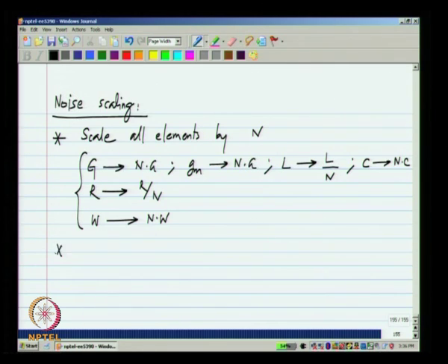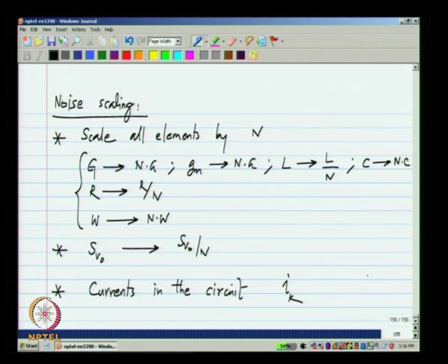If you do all of this, the voltage noise spectral density at any point in the circuit, between any two nodes, will scale by a factor n, and currents everywhere in the circuit, including the supply current, let us say I have some branch current I_k. This is not just the small signal current, it is the total current, will become n times I_k, and this obviously is true for the supply current as well. So, the power dissipation becomes n times the power dissipation of the original circuit.